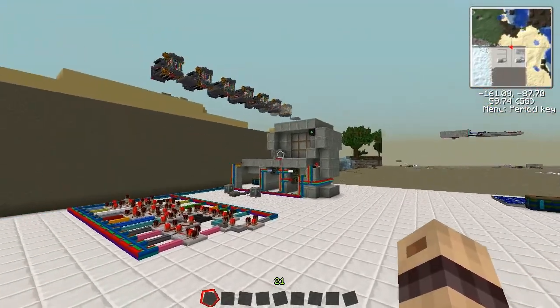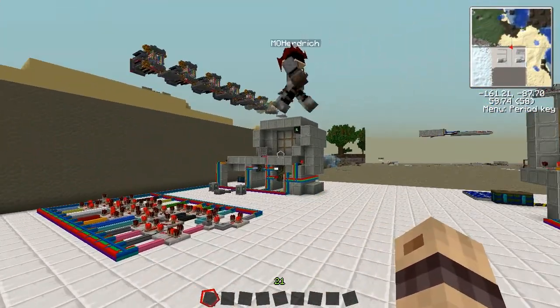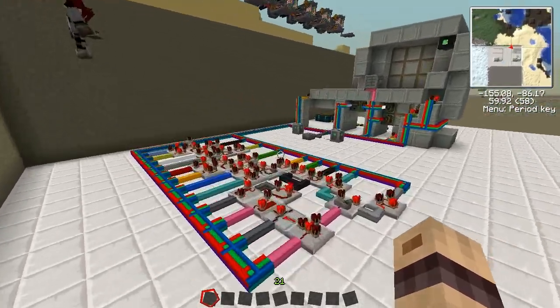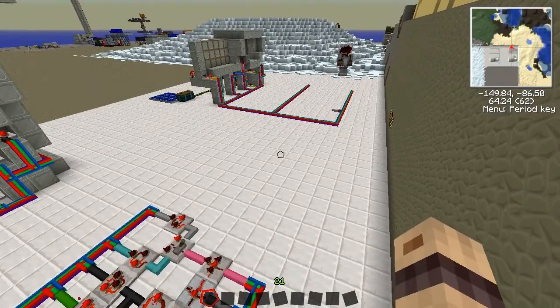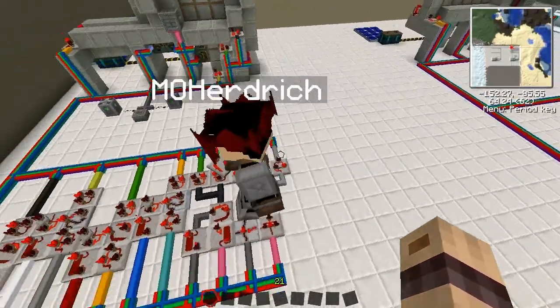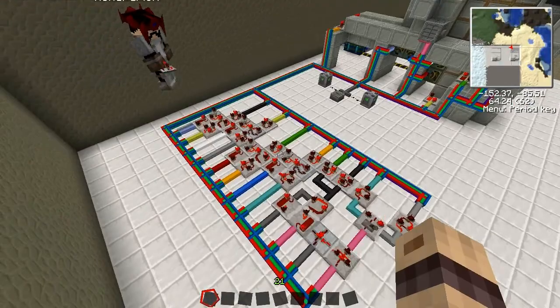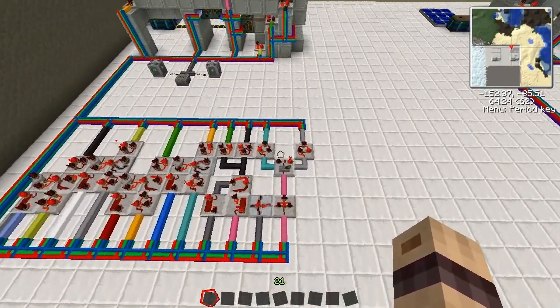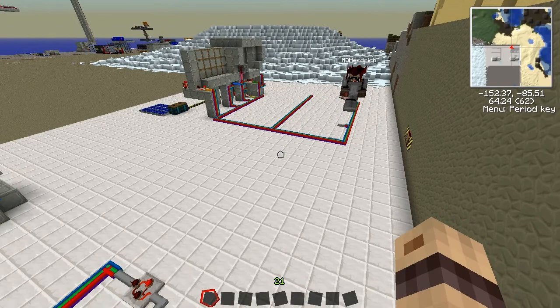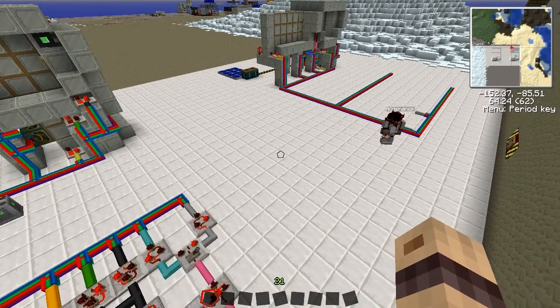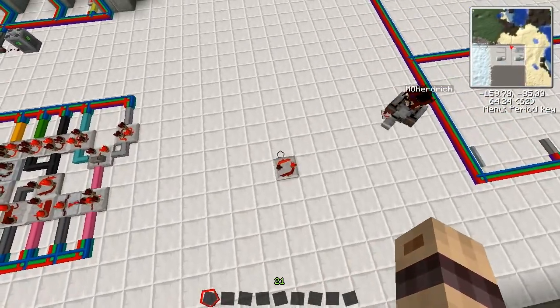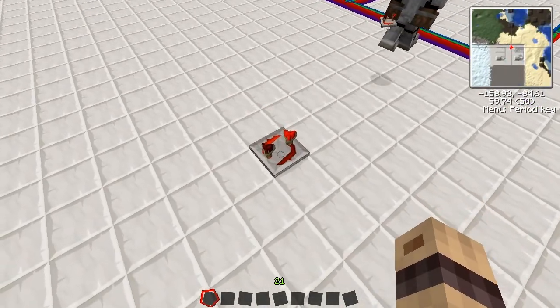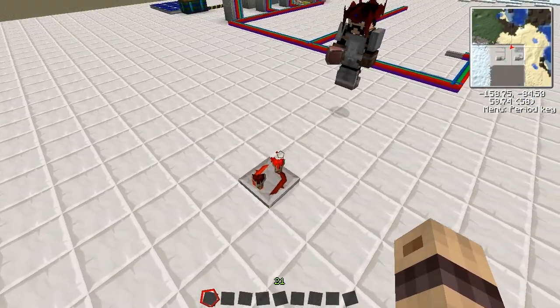Okay. For the logic, we need some basic understanding about what's going on over here. And I think we should start with the concept of so-called state cells. These will basically keep track of the actual status of a door, whether it's moving, what part is moving, and so on. And to do so, we need this little fellow here, called an RS latch. It's basically something like a 1-bit memory cell.